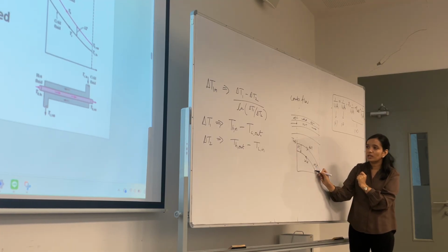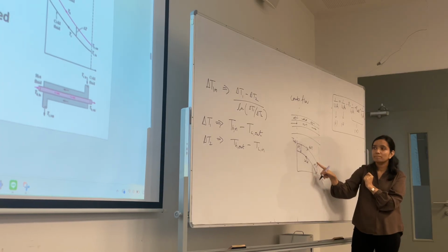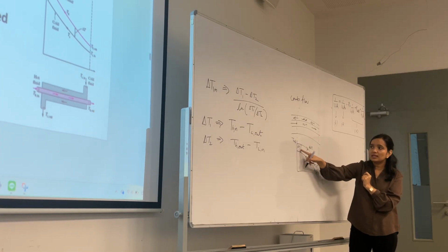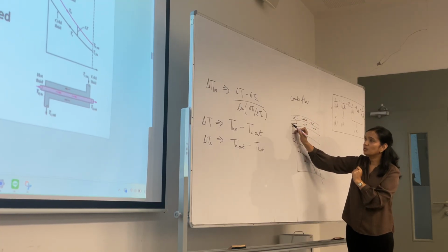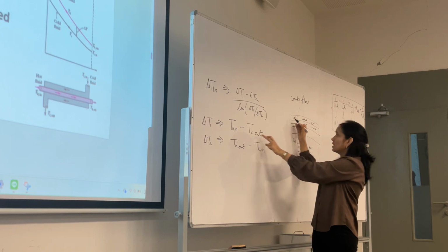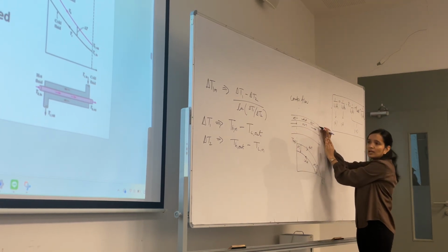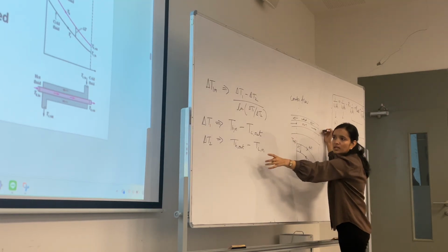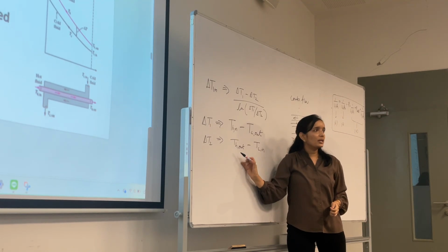So what is delta T1, delta T2? In here, this is delta T1. If you see this graph, hot water in, cold water out. This is your delta T2, cold water in, hot water out. We will always keep this as positive because this is higher temperature.